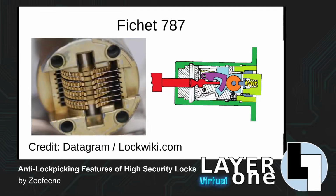We also have the Fichet 787. This uses a very complicated mechanism. I've coloured in the patent diagram that I've found on Lockpicking, and essentially this red portion is the key. The key directly interacts with some levers. The lever then turns a gear. The gear has a gate, and here on the left-hand side we can see all those gates aligned.